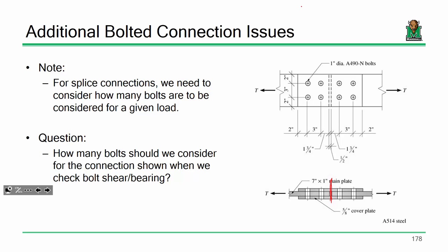You mean here? Not really. Just keep it simple. So let's keep it simple. Your bolts are going to be spaced at 3 inches. You're going to size these based off of minimum edge distances. Going back to our last example, the bolt spacing was 2.5, but the edge distances were 1 inch. So there'd be 1 inch here, 1 inch here, so you'd have a little bit of a gap. 2 1/4. Wow. We'll go with like 2.1 or something. That wasn't even that big of a mistake.